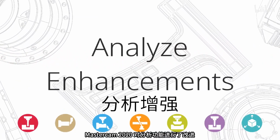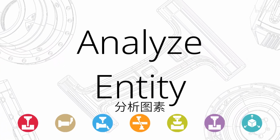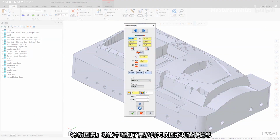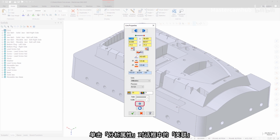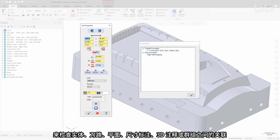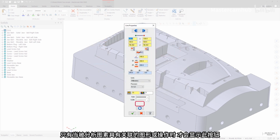Mastercam 2020 includes a number of enhancements to Analyze functions. Analyze Entity now includes additional information about associated geometry and operations. Click Association in the Analyze Properties dialog box to check for association to a solid, toolpath, plane, dimension, 3D annotation, or group. This button displays only if the Analyze entity has associated geometry or operations.